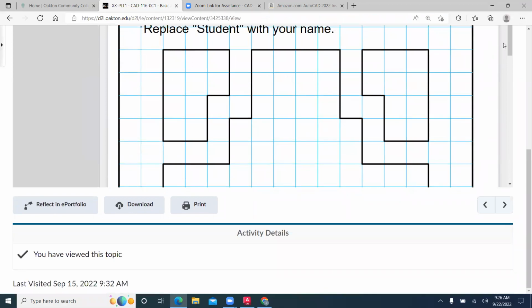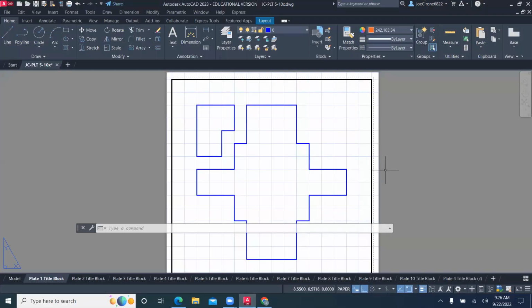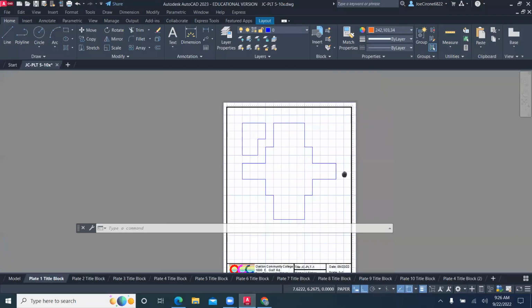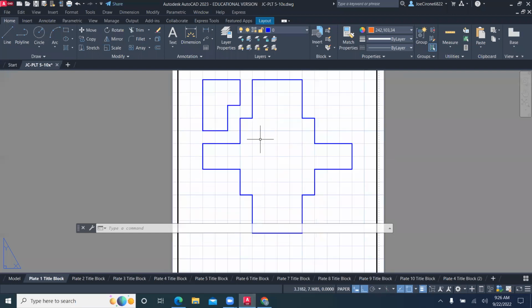And so we'll create these different drawing assignments, and they'll look like this. Here's an example of our first drawing assignment. Typically, people can work their way through the assignments, where we'll start with these draw commands. We'll set up a grid and a snap, and then we'll create these drawings. I think I'm drawing in orange, but that's fine.